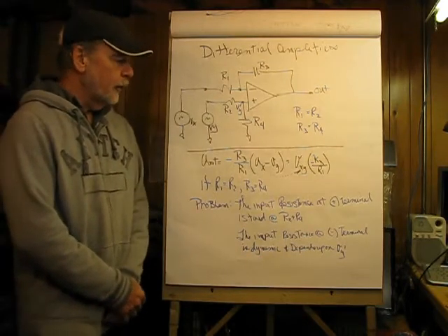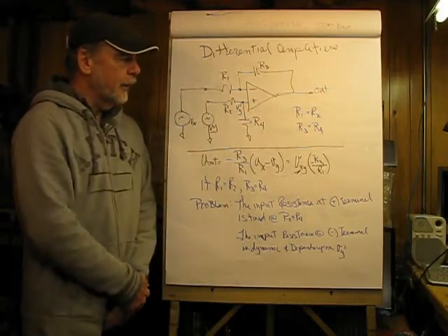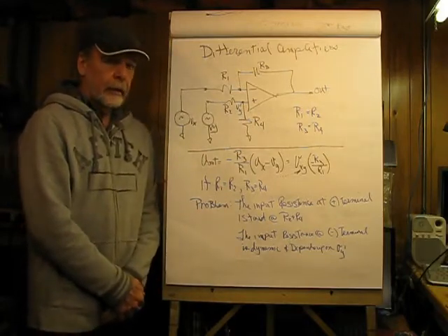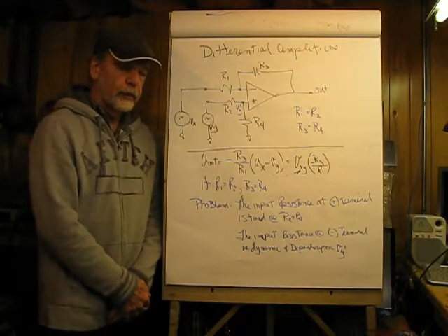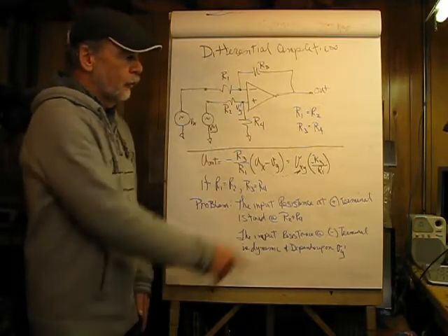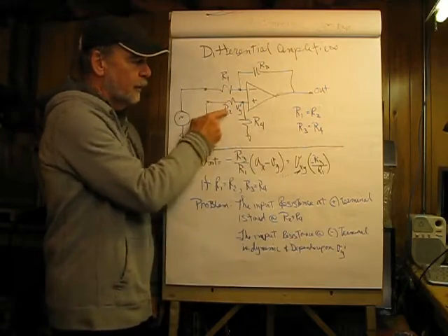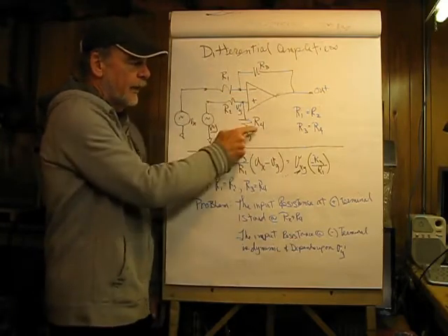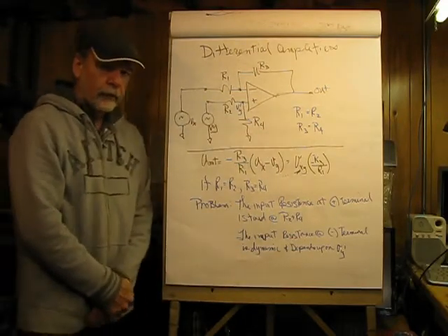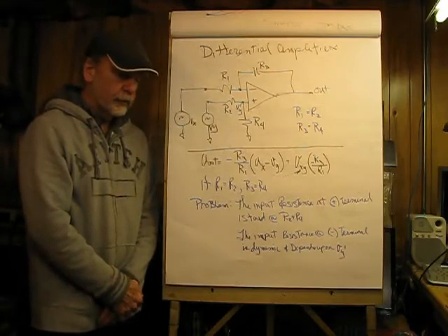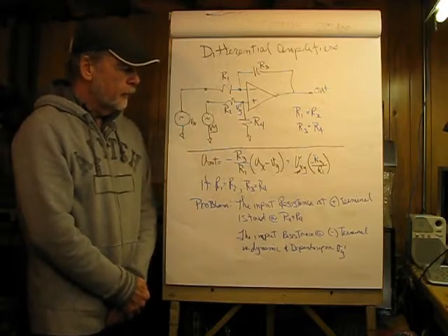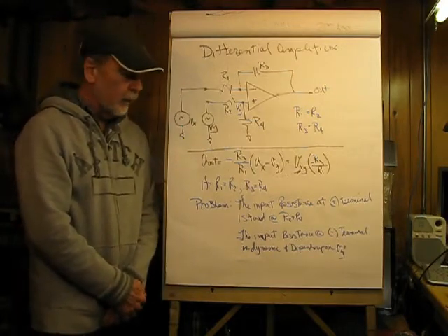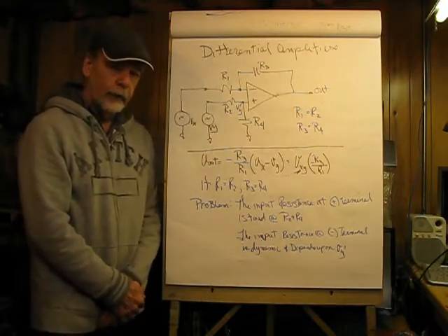And you see on the first schematic here, differential amplifier performance is quite good if certain criteria are met. And do notice the relationship. R1 has to be equal to R2 and R3 has to be equal to R4 for this to function as a true differential amplifier. Now the problem with it is the input resistance of the inverting and non-inverting.